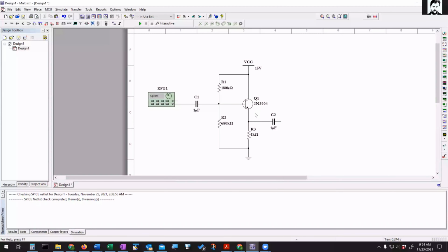So if you think about it, we basically want 7.5 volts to be across the transistor here if we have a 15 volt supply. So what that'll typically mean is that you want about 7.5 volts here, DC, and then up here you'd want to have about 0.7 higher. So you actually have to set a pretty high voltage divider. But this is going to be a little different because from the Thevenin perspective, this is not going to satisfy that beta RE greater than or equal to 10 R2 because of the values I've chosen here.